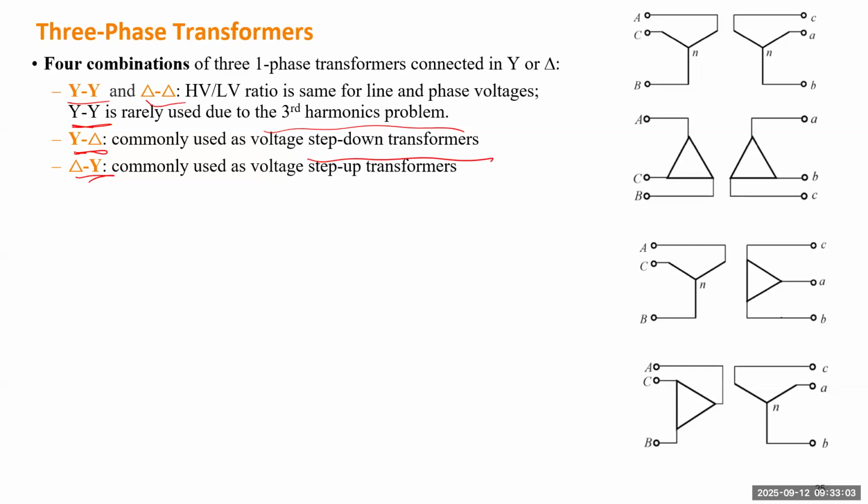You just connect 3 such transformers to behave as a Y to delta connection. That already steps down the voltage, because on the primary side you use line-to-line voltage, and on the secondary side you only use line-to-neutral voltage, or single-phase voltage.